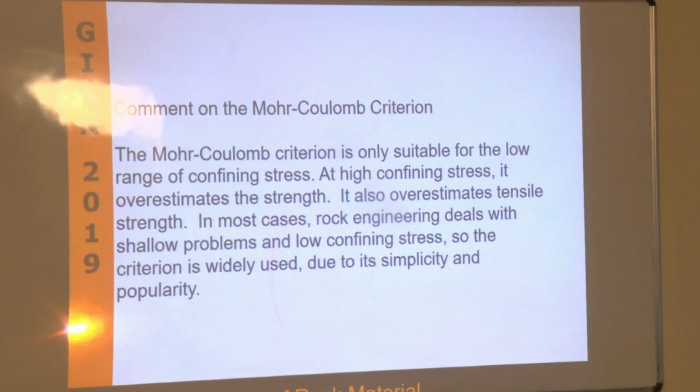Again, that is extremely widely used. But one of the problems with the Mohr-Coulomb is that it assumes the failure to be along a shear plane. So it's basically a shear plane. But that's not the case, for example, along excavations, where it's not really shear failure, it's more a tensile crack that develops. And that is where the Mohr-Coulomb falls a little bit apart.